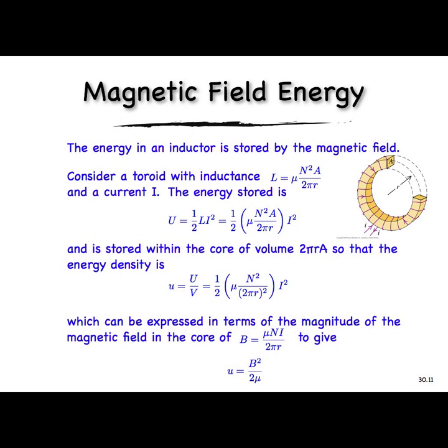And so as the current changes, we can figure out how much energy gets deposited in the inductor. So the energy is just the integral of power integrated over time. So I'll integrate from some initial time 0 to some final time t. I'll write power as iL di dt. So iL di dt times dt, and the dt's cancel out. So I'm left with iL di.